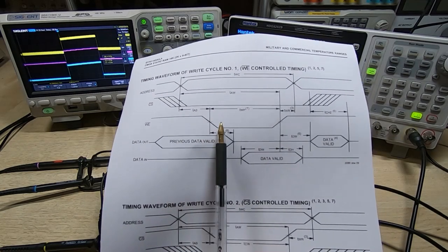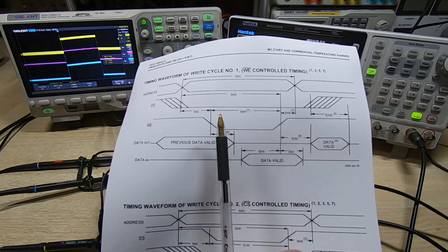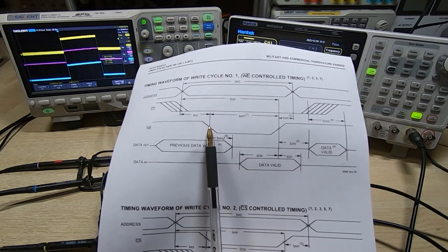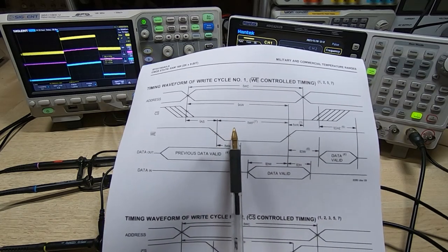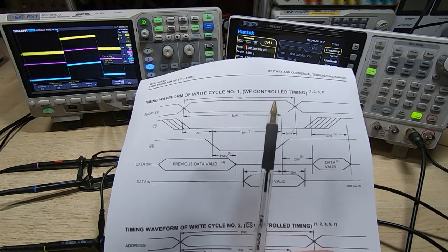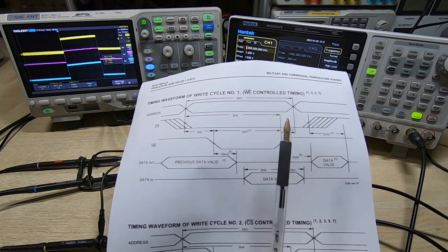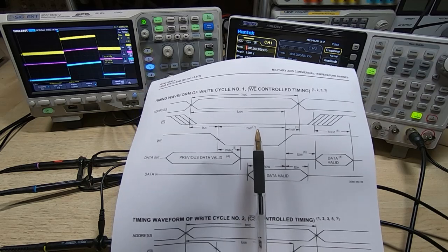And how you go about timing all this depends on how you want to drive your memory and what other devices you intend to drive. But the point here is that the timing is not based on a race condition, it's based on the requirements of the system, based on the clock cycles that are being provided to the processor. Now you can of course introduce wait states and whatever else, but there's a limit as to how far you can go down that path.